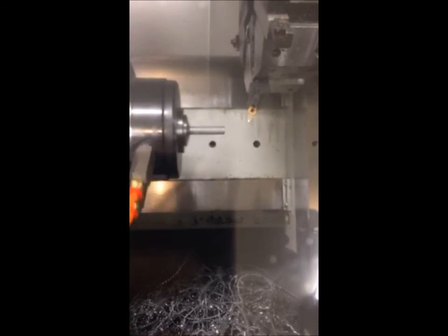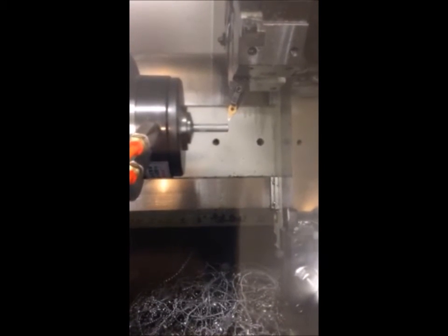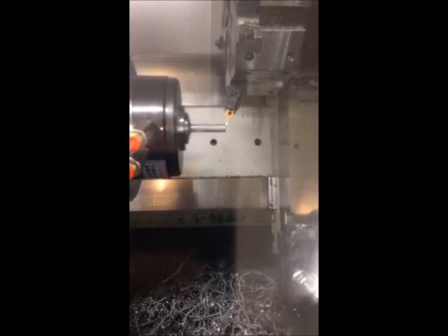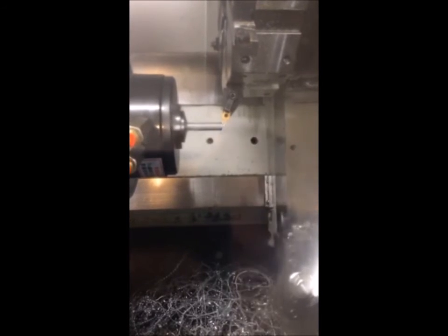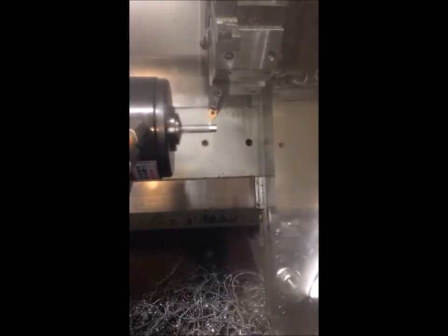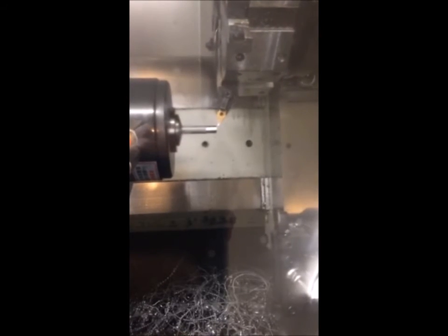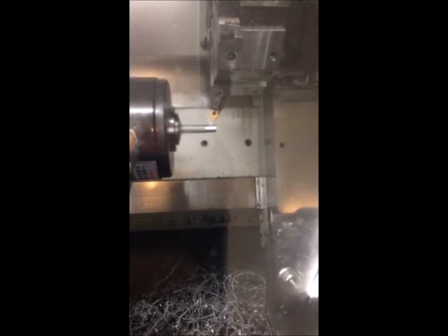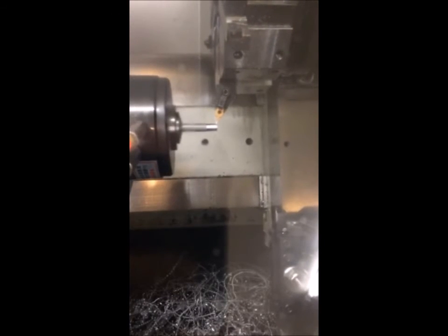The first step of manufacturing this part is to put a piece of straight tubing into a slant bed CNC lathe. The first thing that the CNC lathe does is it faces the part, and what that does effectively is ensure a perfectly square end to the tube. The next thing we have to do is we use the lathe to turn down the diameter of the tubing to make it a little narrower so it can accommodate the flex hose that has to slip over it. So that's what it's doing right now.